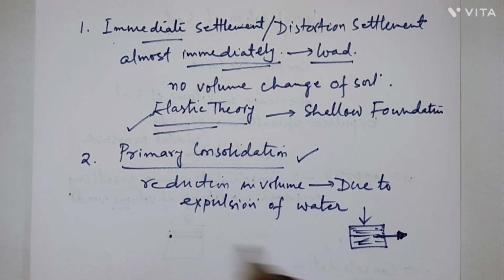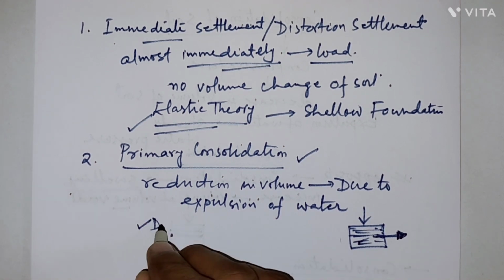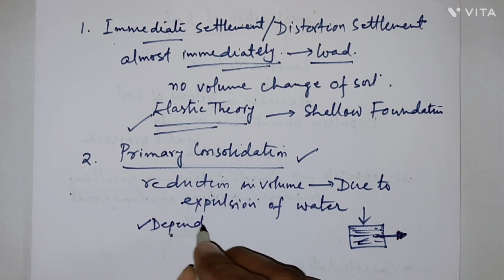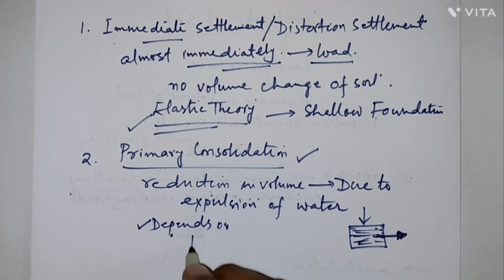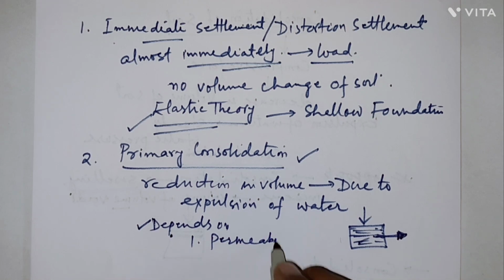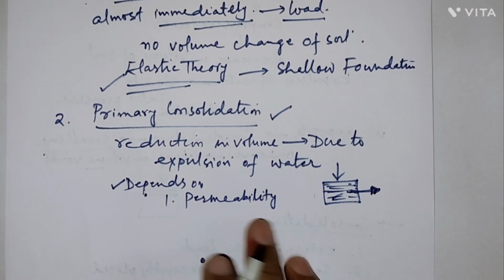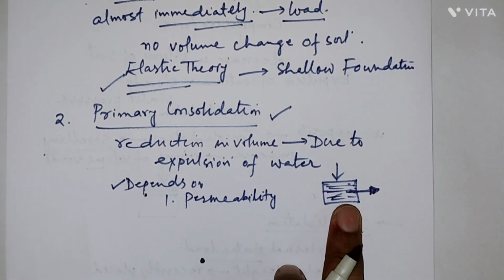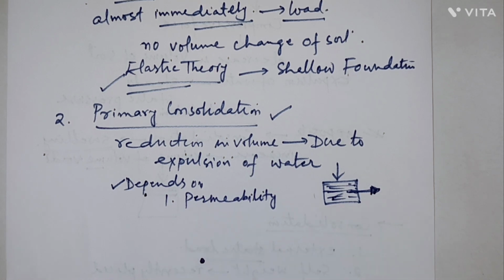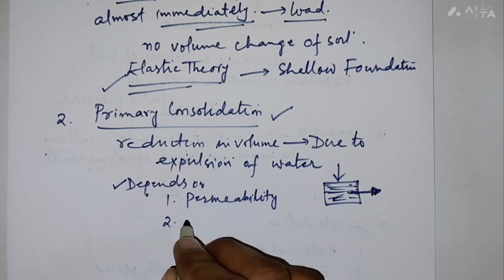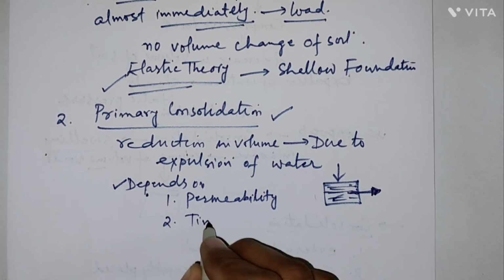It depends on, number one, permeability of the soil. If the permeability of the soil is more, the rate of expulsion of water will be more, so the consolidation will be more. And it is also time dependent.